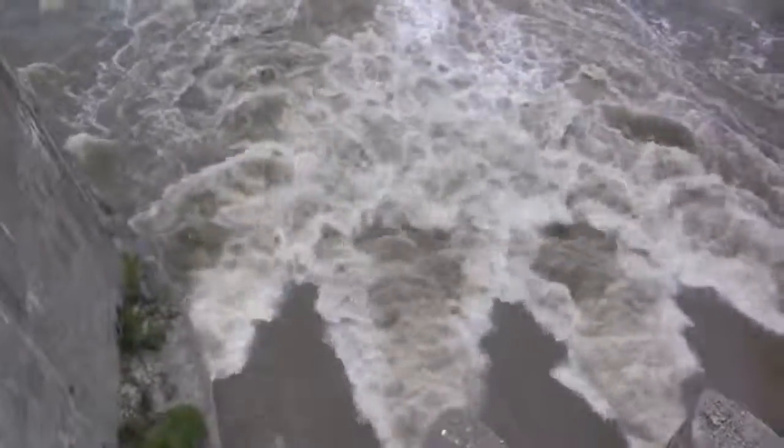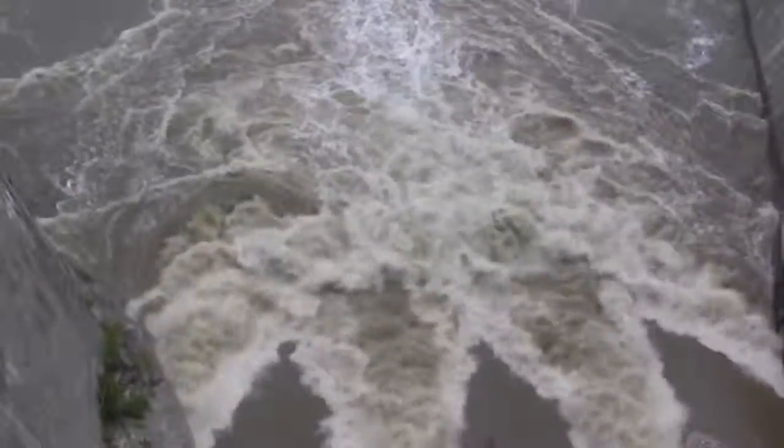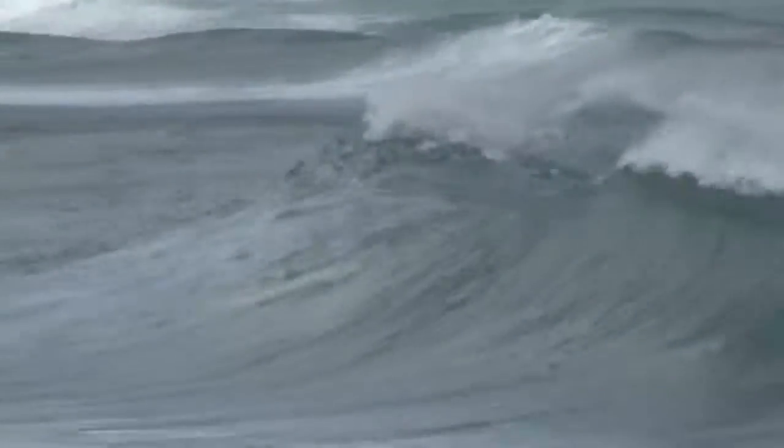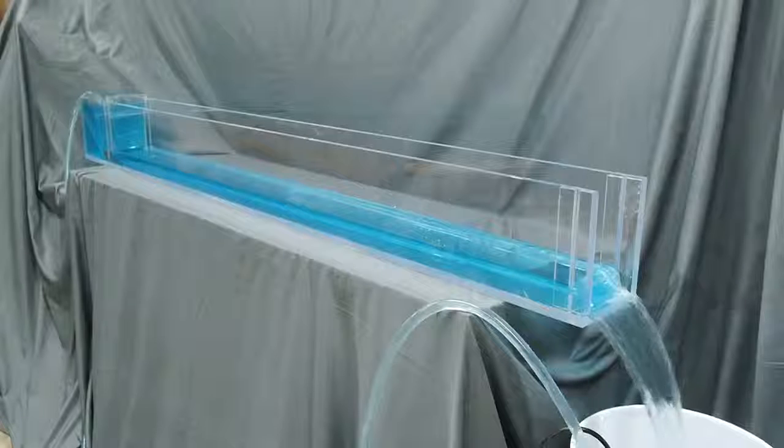But the velocity of flow isn't the only velocity that's important in fluid dynamics. We also care about the velocity of waves, or how quickly pressure disturbances in a fluid can travel. If the flow velocity is exactly equal to the wave speed, we call the flow critical. But it's more likely that these two velocities are different.